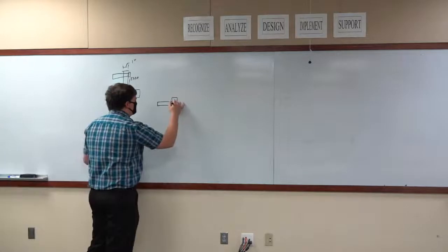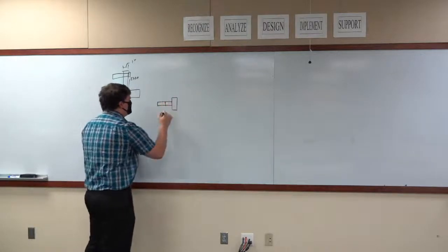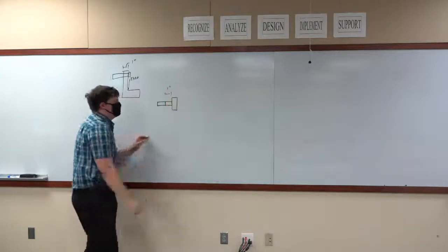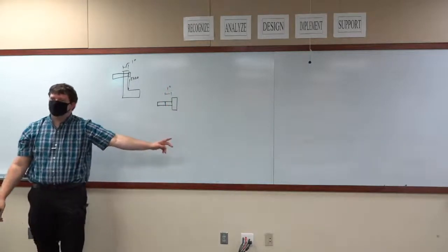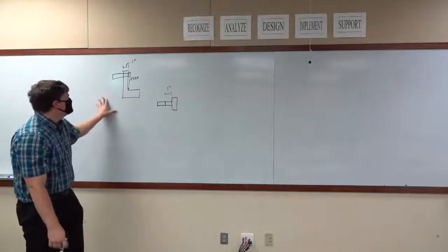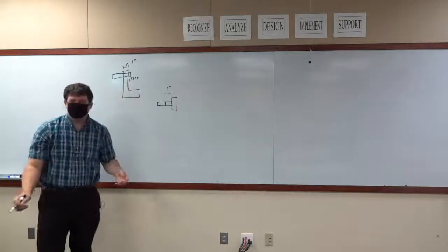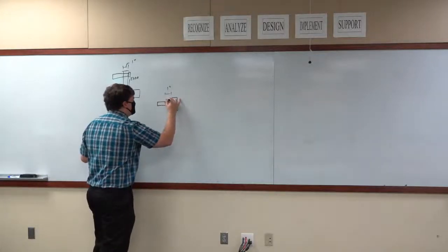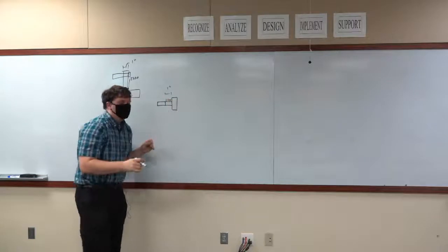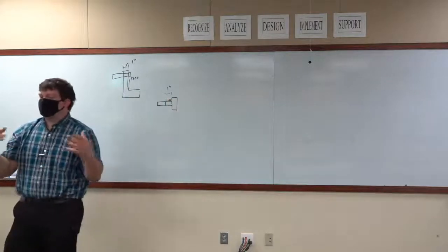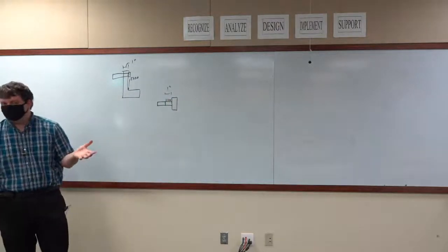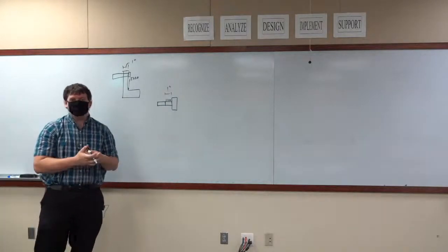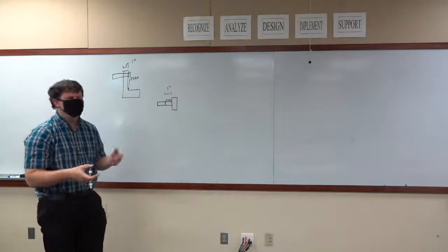What you have here is you basically have 1 full inch on this bolt where you're going to experience any load. Now, generally what we're going to assume here, to make this simpler, we could try saying this is 2,300 pounds of some kind of distributed load, which is realistic, but we don't know what that force distribution is going to look like. And quite frankly, we could spend a ton of time trying to figure that out, and it's not really going to give us a better answer.